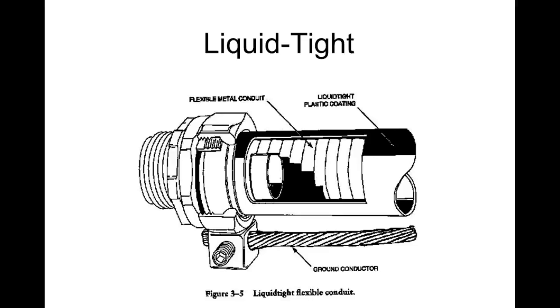You understand? So if we use a liquid tight connector, normally we have to have a grounded conductor that takes the metal and passes it on. I don't think we got any of these over there, but so liquid tight. If we break the ground with a liquid tight connector, then we're going to have to reestablish the ground, right? Everybody understand that?